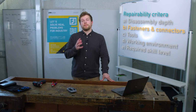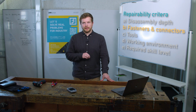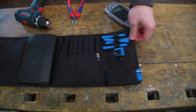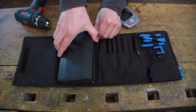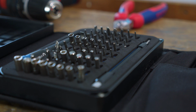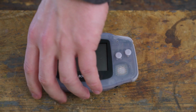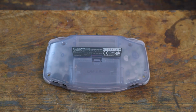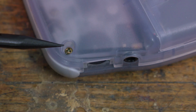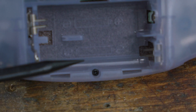Another good design for repairability practice is to reduce the variety of fasteners and connectors. This means, for example, using only one type of screw in your design and thereby requiring fewer tools and less sorting of screws during the disassembly. This old Game Boy Advance is a bad example. Nintendo mostly used 3-point screws, but if you open the battery bay, you will find a typical Phillips screw.